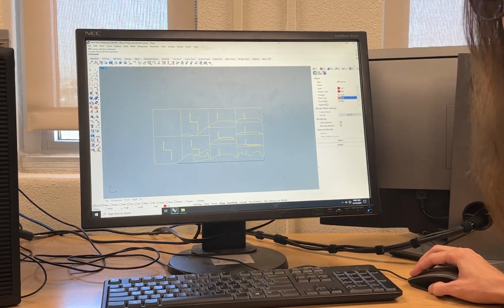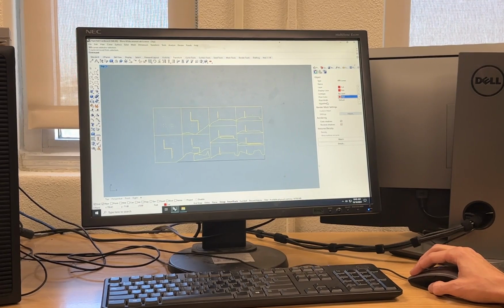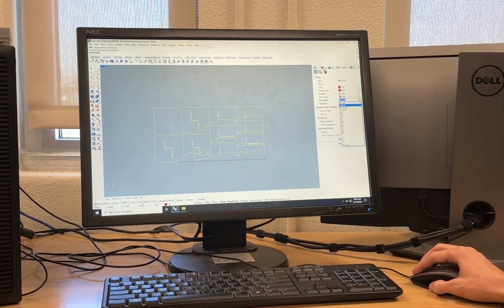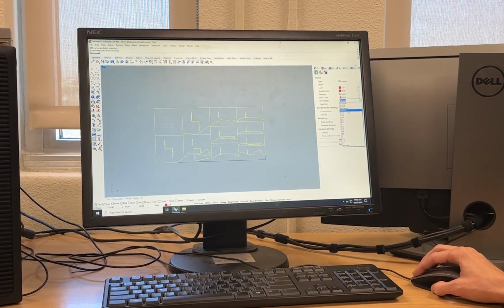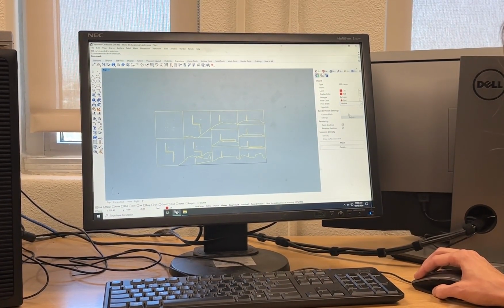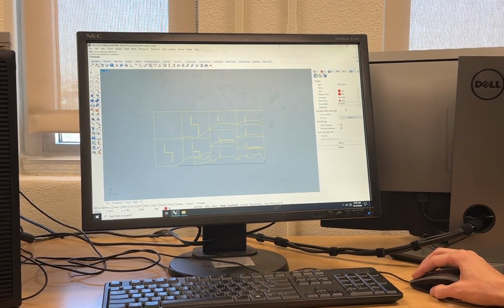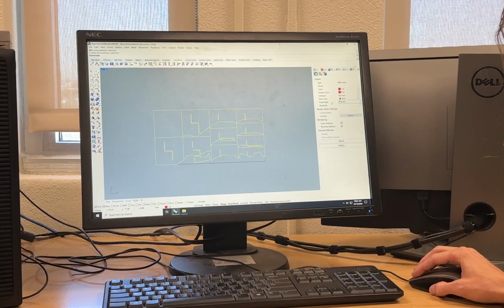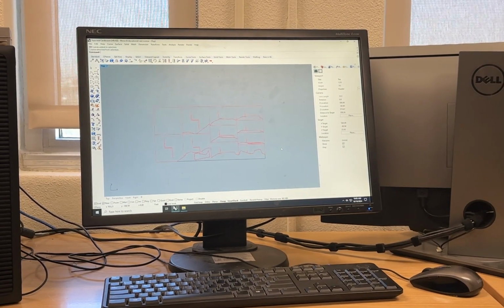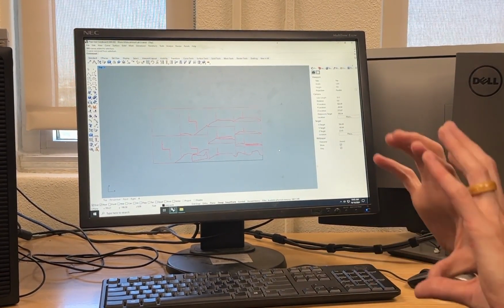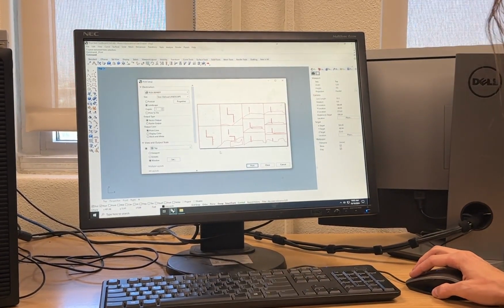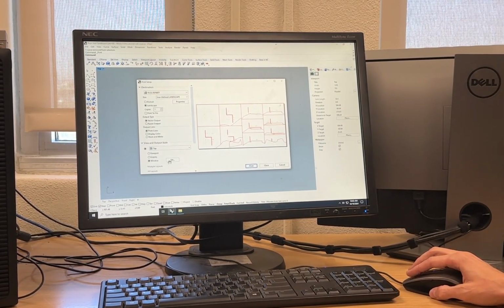My print width is set at default, and usually that does work, but just in case default isn't set to the right default, what's needed is hairline, right? Because this does print at 0.001 of a millimeter, which happens to be known as a hairline line type. In our case, it's the print width, but now we're good to go. But to be fair, nothing visually changed. So keep in mind that we have to change the settings of those lines. Same process though, we'll do Control P for print. And honestly, once you do the window set, you're good, right?